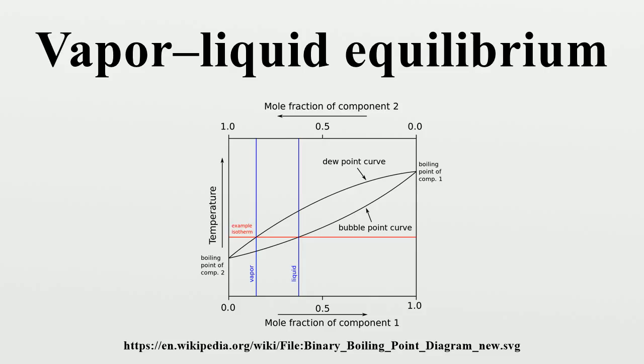For many kinds of mixtures, particularly where there is interaction between components beyond simply the effects of dilution, Raoult's law does not work well for determining the shapes of the curves in the boiling point or VLE diagrams. Even in such mixtures, there are usually still differences in the vapor and liquid equilibrium concentrations at most points, and distillation is often still useful for separating components at least partially. For such mixtures, empirical data is typically used in determining such boiling point and VLE diagrams. Chemical engineers have done a significant amount of research trying to develop equations for correlating and/or predicting VLE data for various kinds of mixtures which do not obey Raoult's law well.